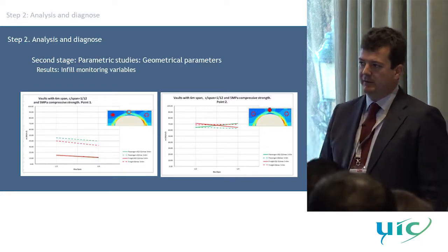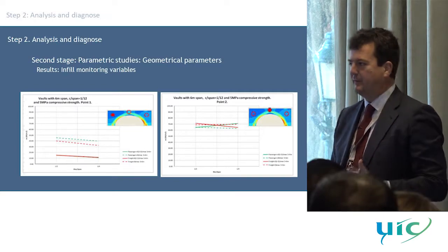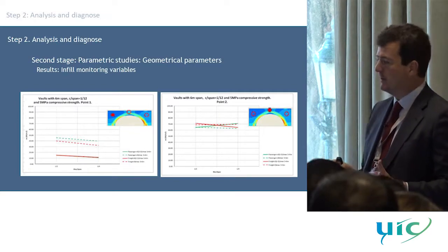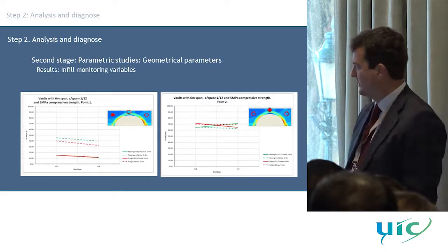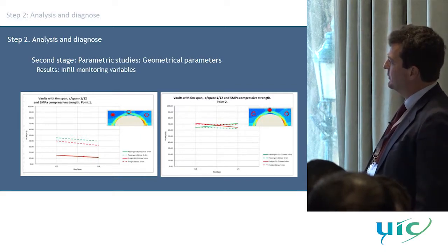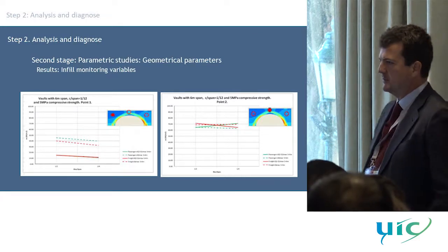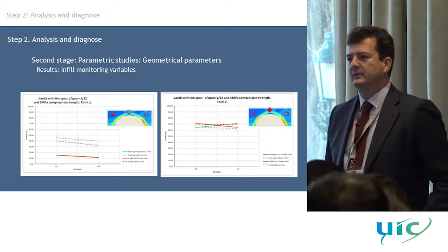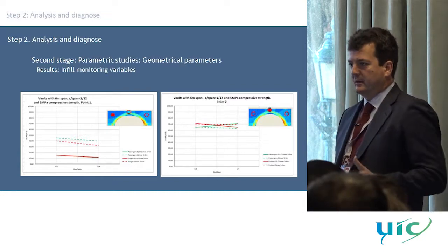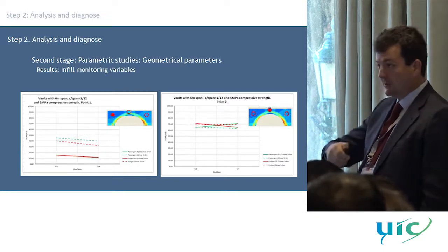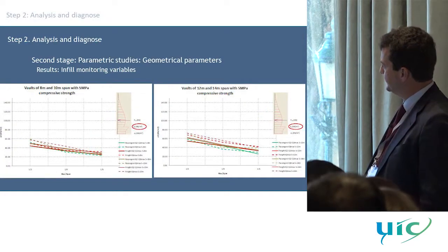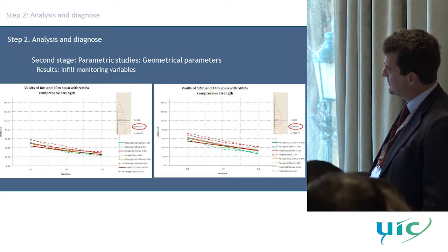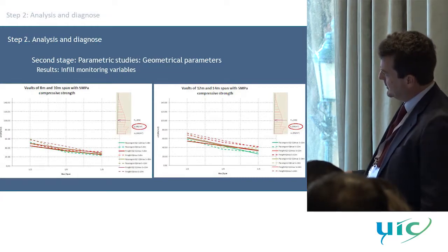We will go on the strip, the effective width that we took into account, but there are no spandrels here, okay? So it's an over-conservative analysis. And if you move to the infill pressure, they are nonsense. I mean, they are very, very little. You cannot explain a bulging of the spandrel due to the horizontal pressure that you have in the infill according to this analysis.